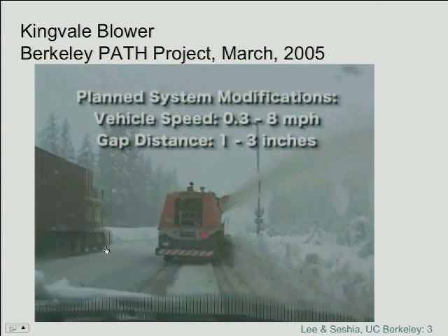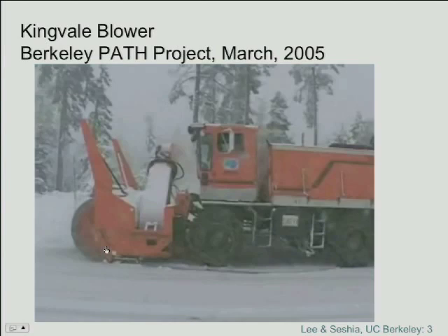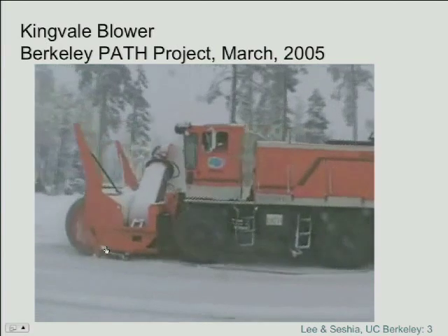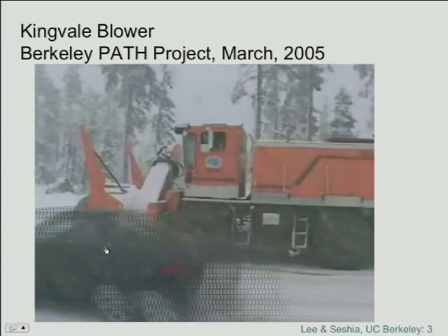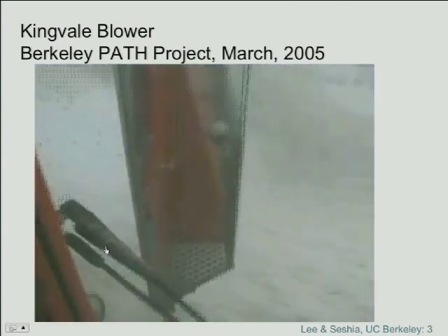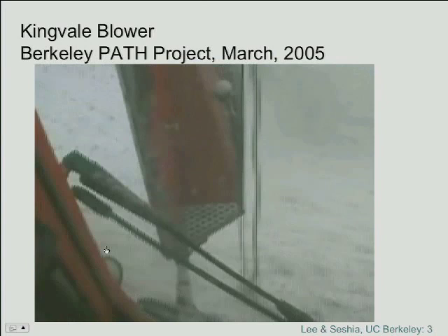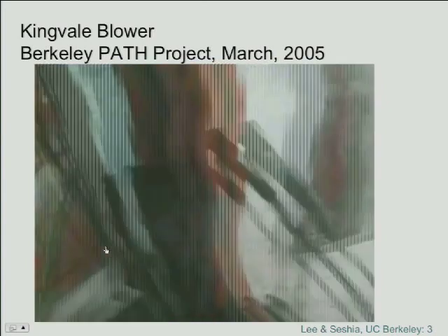Maybe a Hall effect sensor for finding the guardrails. Okay, so one possibility would be something that would sense the guardrail somehow. How would it sense the guardrail? Use a Hall effect sensor, so you could generate a magnetic field. You'd assume that the guardrail was some ferrous material, and you would measure your distance to that guardrail.